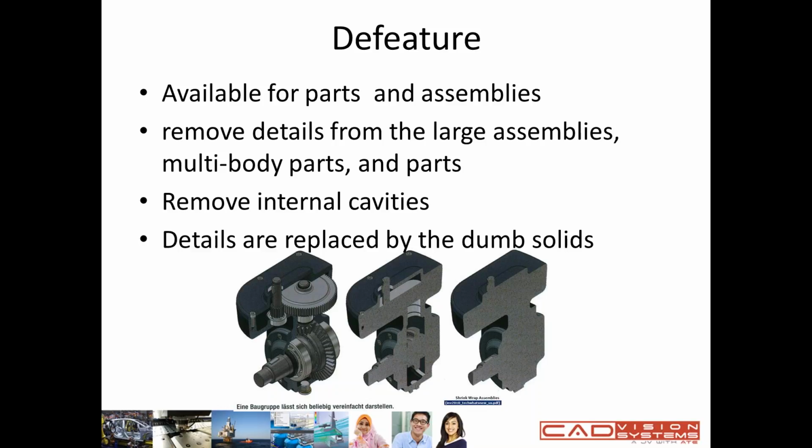You can do this in parts or assembly. Basically it removes the details and also removes internal cavities, and the details are replaced by a dumb solid. If you look at the picture at the bottom there, when I'm doing a section view, the cavity will just be filled up with a dumb solid.